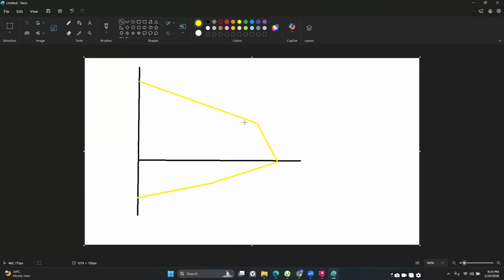So this interactive diagram is basically a failure envelope, if I may say that. And what we do when designing columns is we get to choose the acceptable combination for moments and axial capacity for given members. So if we have a given cross section of a column, the interaction diagram basically shows us the acceptable combinations for moments and axial loads for this given cross section.